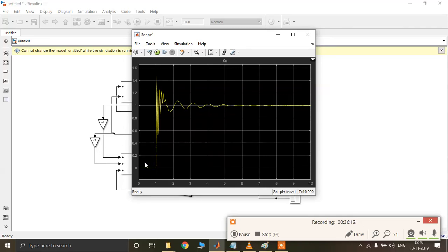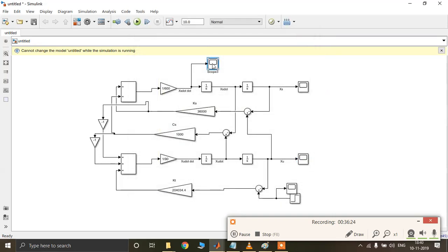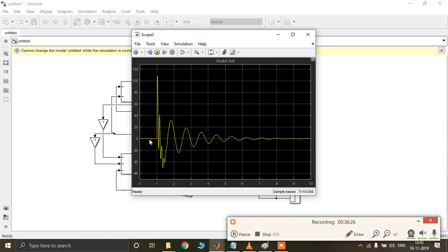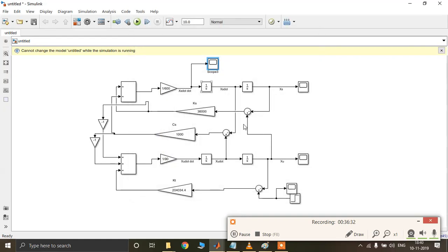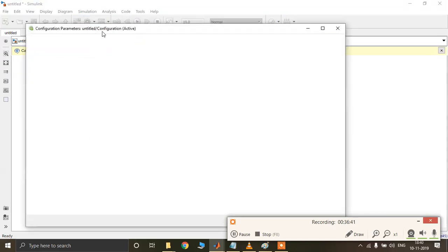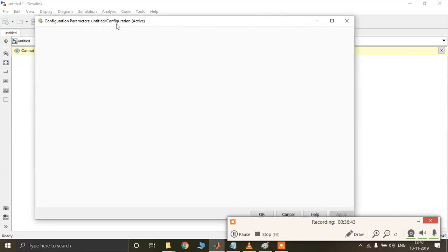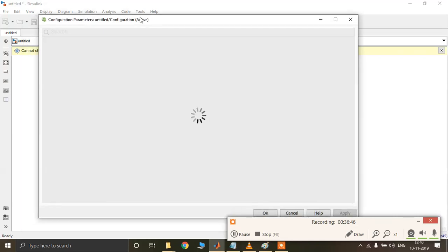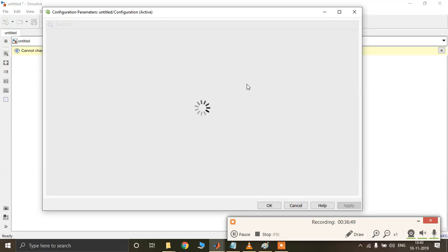Here's the graph for unsprung mass. So as you can see, when the car hit it, how it is going. Now for our acceleration, what happens to the acceleration? This is how the sprung mass acceleration is varying. At 1 second. So this is how it generally runs. You can change timing and other things using this model configuration. So it has various functions.